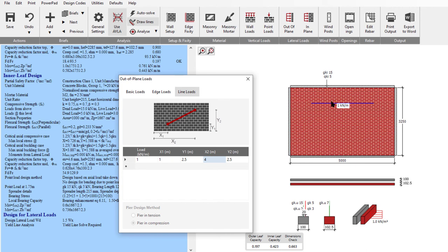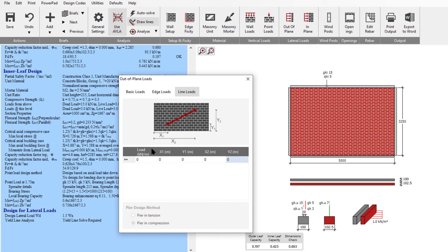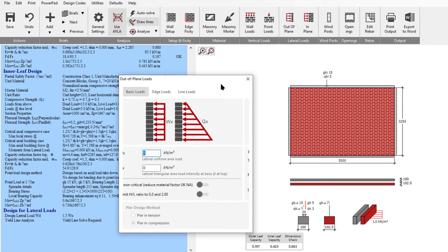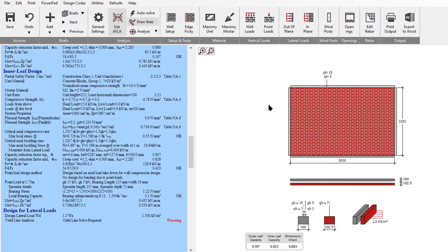You can also turn around and use this with a wee bit of lateral thinking. If you said, well, actually, I want to apply a 2.5 kilonewton point load onto the wall, what you'd do is you'd say, let's make it 25 kilonewtons, and then let's make it span from 2 meters to 2.1 meters, so 100 millimeters. So you'll find that that 25 kilonewtons will equate back down to 2.5 kilonewtons in that localized area. And it's very, very useful. I am going to take that and just delete that line load. I'm happy with everything else. So a wee bit of fun and games with loads.